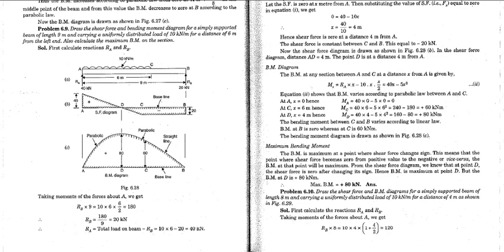So we are going to use this equation shown over here. We know that shear force equals 0, so the force of 40 is applied over here, minus 10 times x, and at this point the shear force will be equal to 0. By this way we can calculate the shear force at this section.